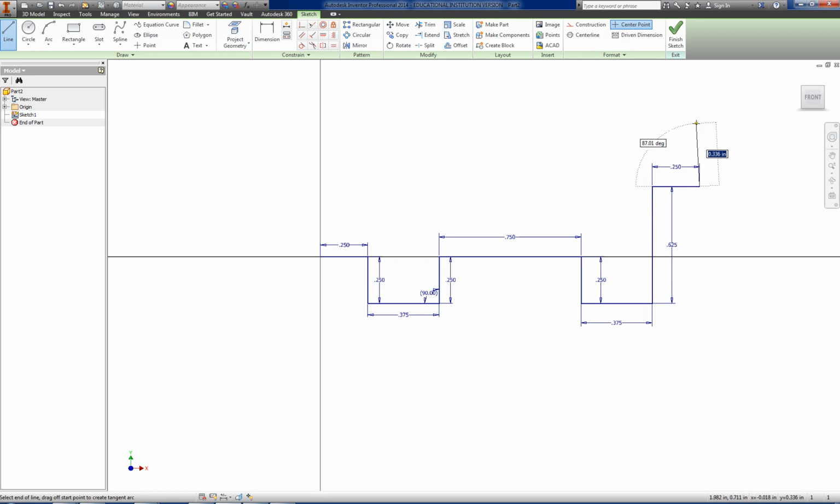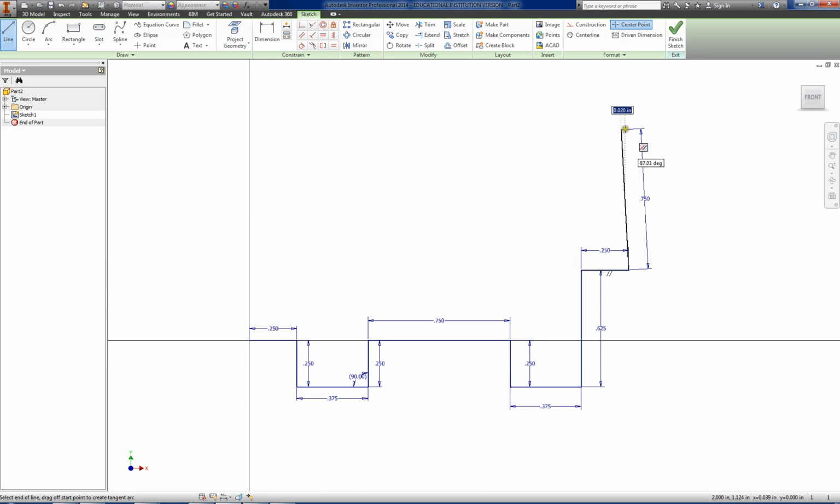Now this is one way you could go about doing this. If you don't like putting your dimensions in all at the same time, you can draw a rough shape of it and then go back and add your dimensions there. Now what you'll see here is I've done the opposite. I have the right dimension, but it's not at that perpendicular angle. So I could delete it, I could redraw it, or up here, these are those constraints that we saw before. We saw parallel and perpendicular. I can simply grab the perpendicular and say make these two lines perpendicular, and it will shift it to that effect.